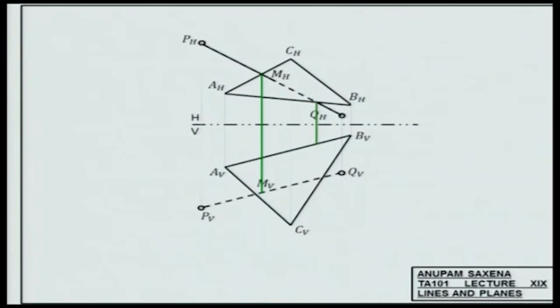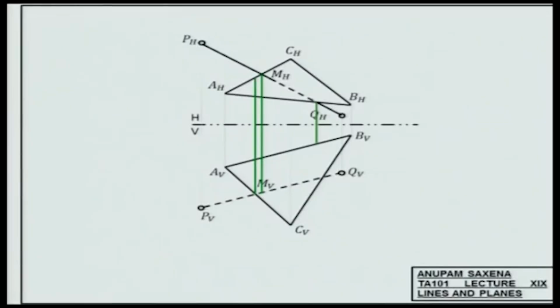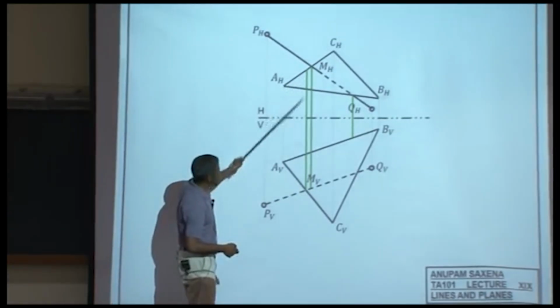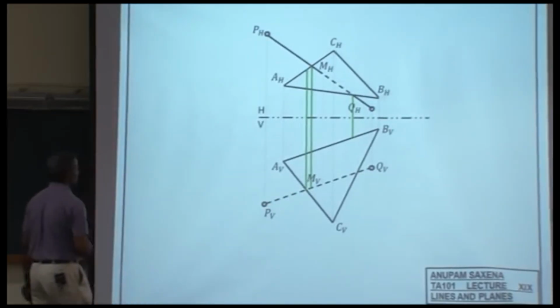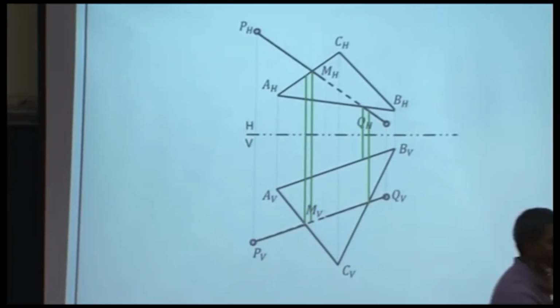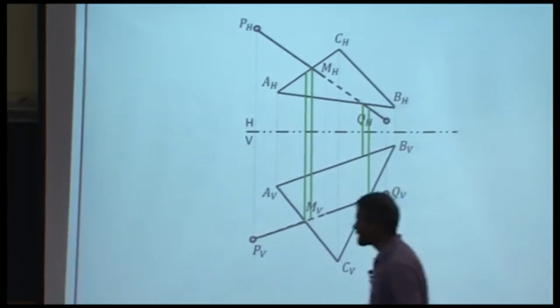Okay, and do the same thing from the bottom. Raise a projection line from here. Okay, so this is the intersection between PQ and AC. AC comes first, so this part of the line will be hidden, and the other part of the line will be solid. Right? So this is a nice algo. But the auxiliary view method, the edge view method, gives you a reason as to why a part of the line will be solid, the other part will be hidden, or vice versa.